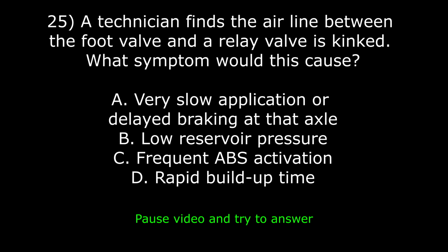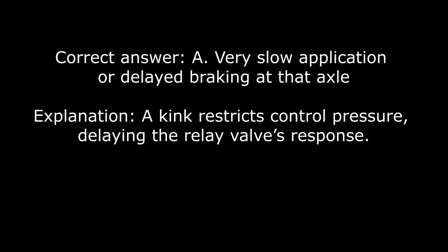A technician finds the air line between the foot valve and a relay valve is kinked. What symptom would this cause? A. Very slow application or delayed braking at that axle. B. Low reservoir pressure. C. Frequent ABS activation. Or D. Rapid buildup time. The correct answer is A.